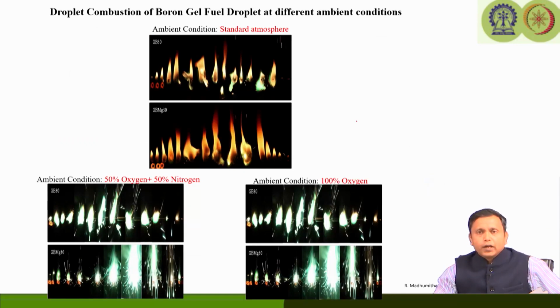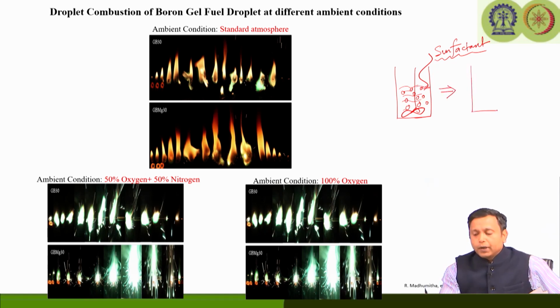Now the problem of boron particles, if you load in a typical liquid fuel system, what is going to happen? You have let us say liquid fuel, you are trying to load some solid particles. You are churning it maybe with something, you may add some kind of a surfactant or some ingredients which can lead to improvement of stability of the particles, but after some time it may so happen that the particle is going to sediment. You may see that you have a clear liquid and at the bottom the particles have settled down, which is not really the requirement for particle loaded fuel, because we want that particle to be dispersed.